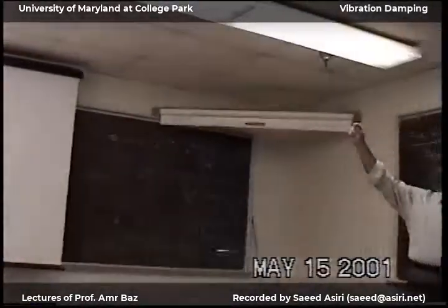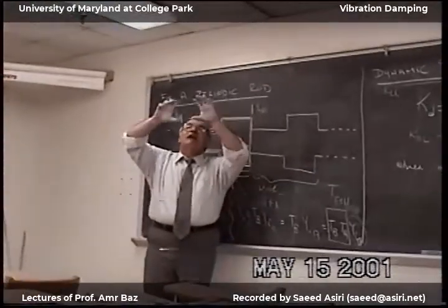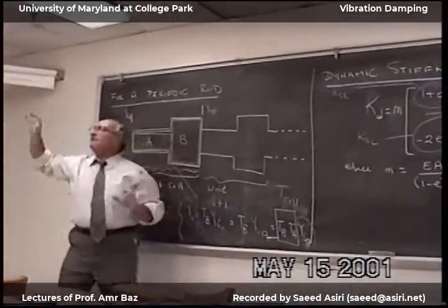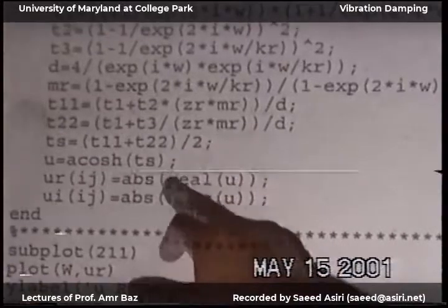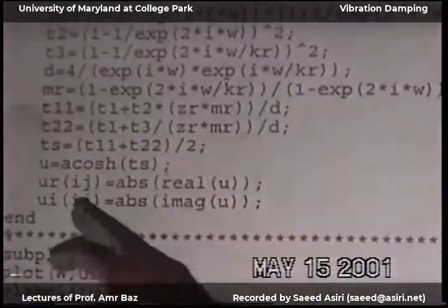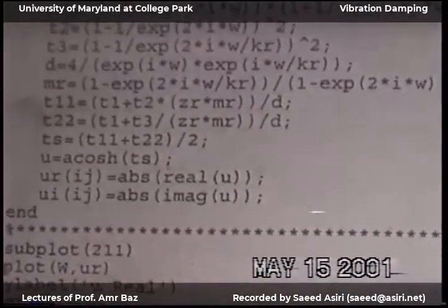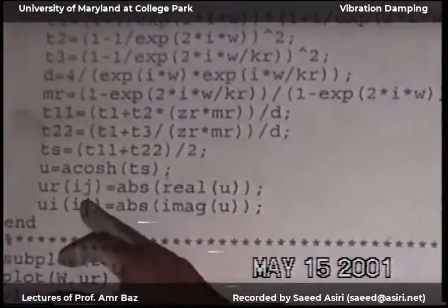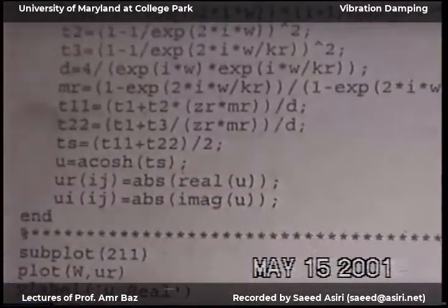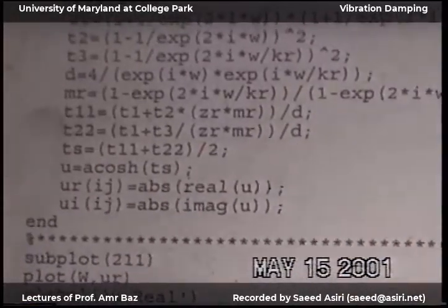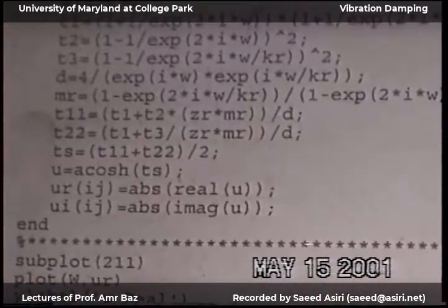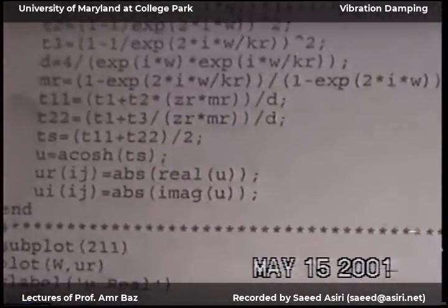From T cell, all what I need is the diagonal elements. And the off-diagonal elements, I don't care about them, because all these two elements, when I divide them by 2, I can get the propagation parameter mu, which is the arc cosine of the sum. I can plot the real part and imaginary part. If the real part is 0, we have pass band. If it is not, then we have stop band. And then I can plot these and look at how the characteristic will look like.